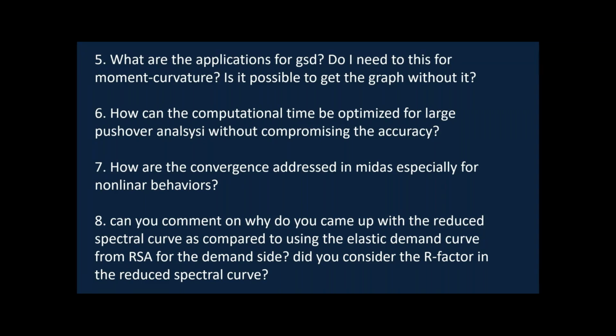Coming to the sixth question, how can the computational time be optimized for a large pushover analysis without compromising the accuracy? It depends upon the way in which the structure is modeled. In the model that we just saw, I have assigned pushover hinges throughout the length of the pile.